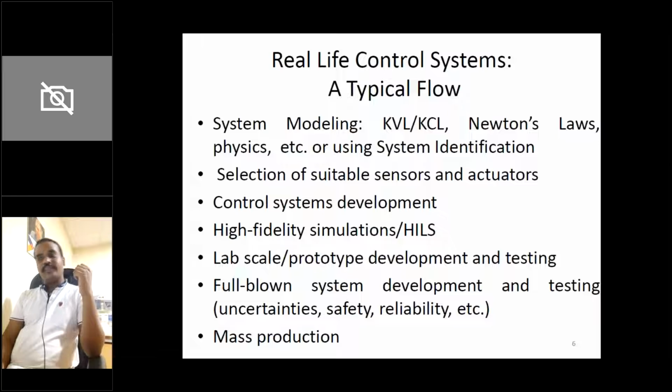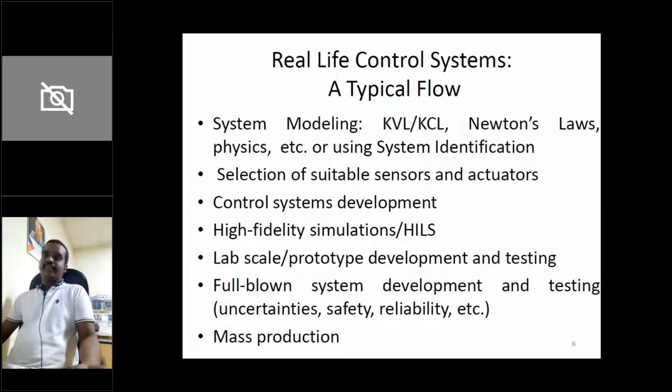And then one has to go with hardware in loop simulations, HILS. Here, it is something in between the simulations and the realistic model implementation. In HILS, some of the components we keep as real hardware, and some components we keep as software. For example, the plant: suppose you want to control a wind turbine of 1 megawatt, a very huge wind turbine. Yes, GE has a few megawatts of wind turbines, the very largest ones. So how will you do that?